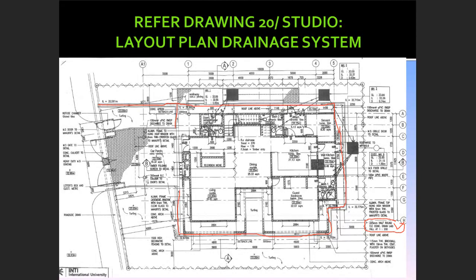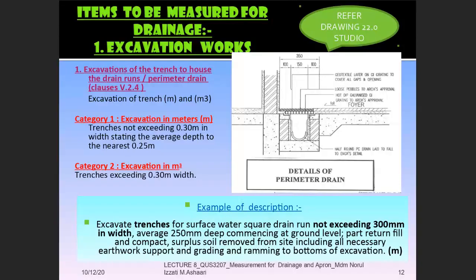So in terms of the width, you can refer to the details, but the length on plan is something like this that you have to follow. The detail length, we will go through later in the studio. But at least I would like to know, if you need to measure the answer in meter, you have to get this layout plan. If you need to measure the length, the width, and the depth, the length is on plan, the width is from the detail, and the depth is where you have to scale until this level. Okay, so that is how you get the first answer to be ready.